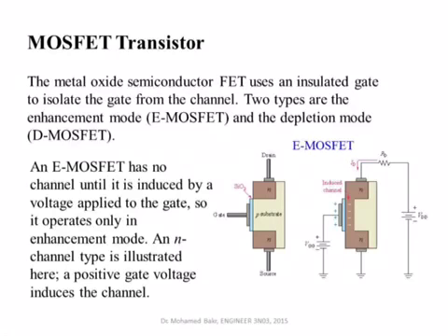Okay, we covered in the previous lecture the JFET transistor. We have seen that in the JFET transistor we have a reverse biased PN junction, and we can control the width of the conduction channel by varying the reverse bias on this PN junction. The MOSFET transistor, which stands for metal oxide semiconductor field effect transistor, applies a similar theory, but it does not really use a reverse PN junction.